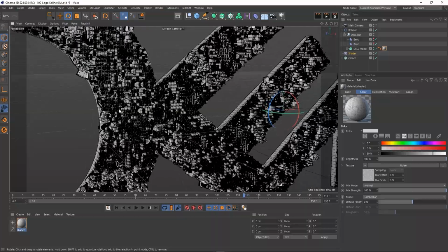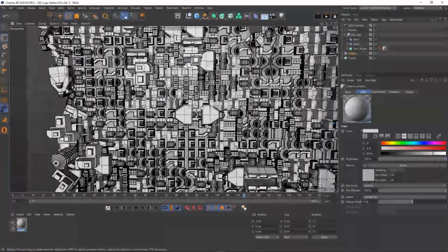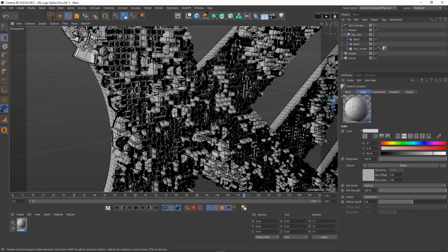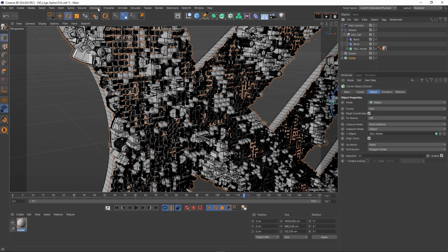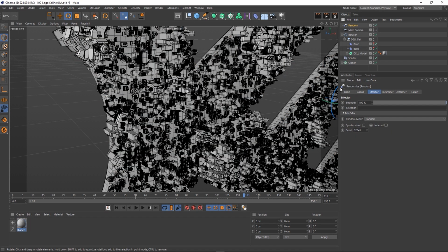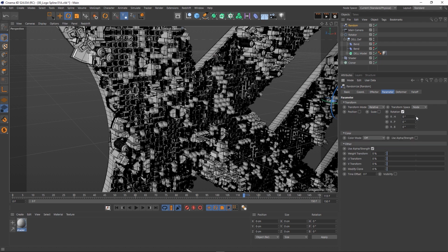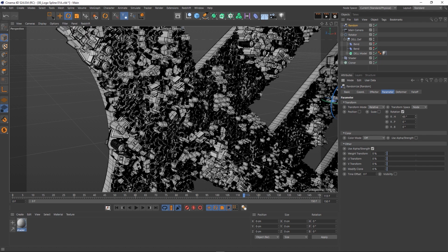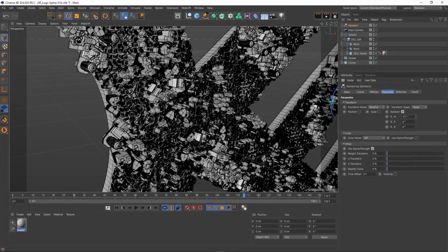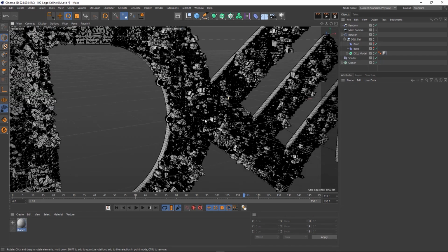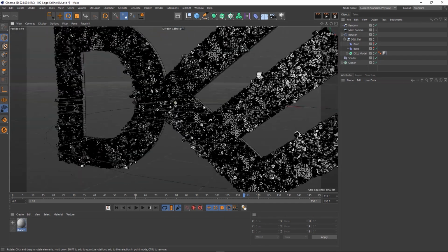Now this looks nice and good, but it's too regular. You can see everything is 90 degrees. So all I want to do is go to the cloner, add a random effector, and set the parameter to be rotation, rotate the H, and now we're rotating these and breaking up that uniformity. I don't care if I have overlaps. That's part of the artistic vision I have. Excellent.